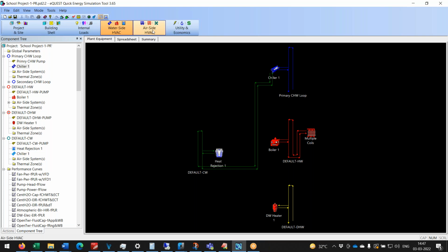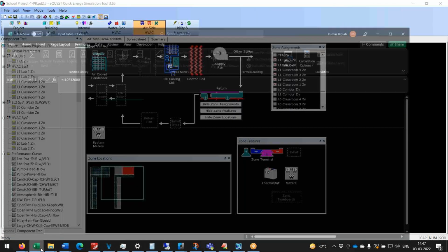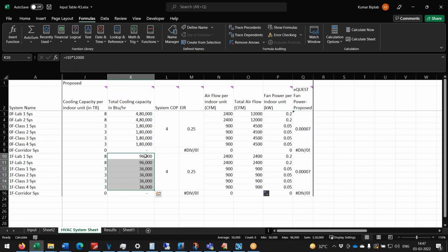Whereas here it is the refrigerant. In the case of a VRF system, it is the refrigerant which is going to the condenser, and the delta T is almost approximately equivalent, if not higher. So in VRF systems, the condenser will either be sized similar to the total capacity, or slightly less. That's something you can rightly say. Diversity factor is taken into account.